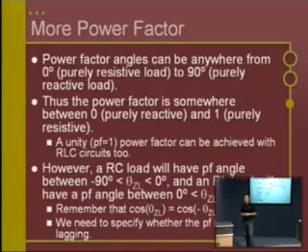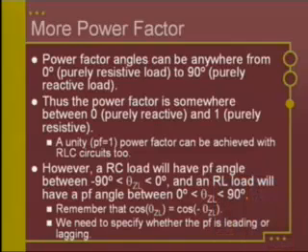Now, however, it is not, strictly speaking, entirely the case that you can't have a circuit that contains inductive or capacitive elements and still have a unity power factor. It has a lot to do with the fact that you can have inductors and capacitors playing off against each other, which will cancel out the influences of the other one.